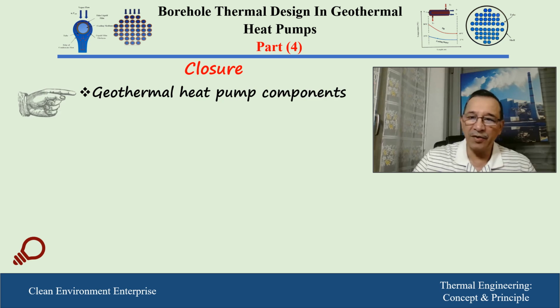We passed through the geothermal heat pump components, the underground part, which represents the borehole, and the other parts, which are on-ground parts, which includes compressor, expansion valve, and either the evaporator or the condenser for the direct geothermal borehole, where we have the fluid passes through the tube, the U-tube, and is the same fluid which is circulated in the heat pump itself.